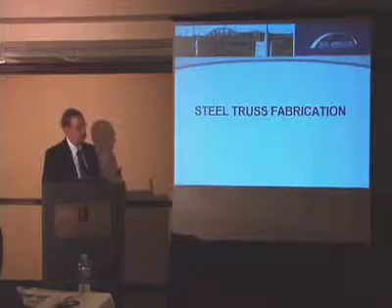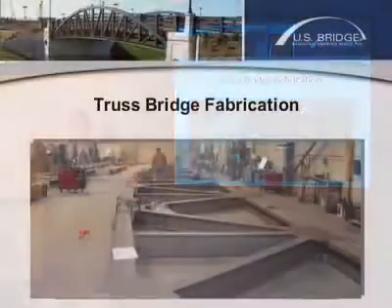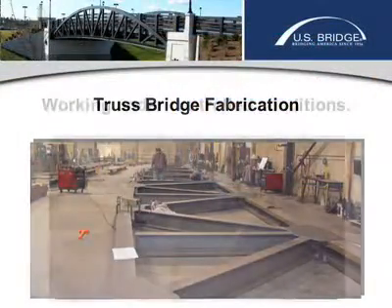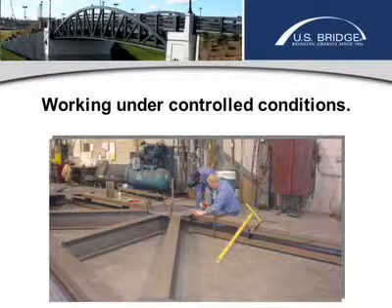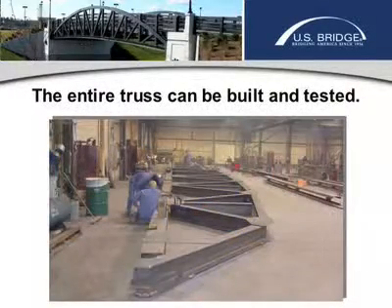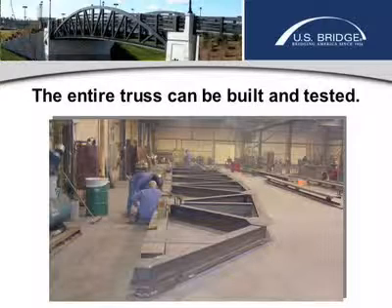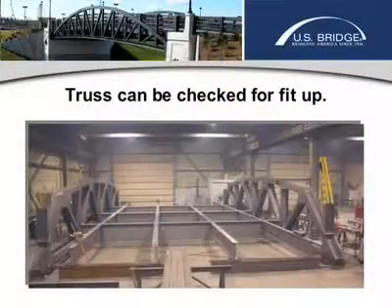Of course, with steel truss fabrication anymore, everything is inside plants under controlled conditions for drilling and welding and all the layout. You can build the entire truss, do all the weld testing, and inspections can be performed. The trusses can, in most cases, be put together and tested for fit up.